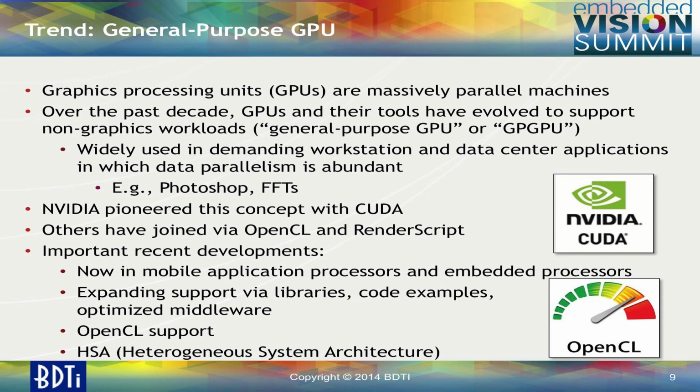Can we repurpose it to do our data parallel, especially the kind of front end, filtering and rectification and edge detection kinds of algorithms that tend to be highly data parallel? And the answer is now changing from not really, or only for the hardcore, really dedicated people who want to get into all the details, to, yeah, actually you can, because here's our OpenCL implementation for our mobile application processor. So that, I think, is a real plus.